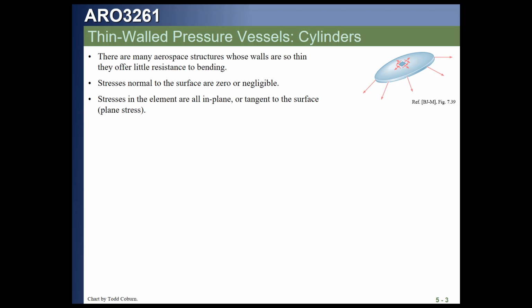If you imagine a balloon, the wall has near zero bending stiffness, but the balloon can carry a lot of pressure because it takes it all in a tangent direction in the plane of the surface. All the loads are carried in tension in both directions, and so that idealization of a thin-walled member with negligible bending stiffness and only axial stiffness is a common one in engineering.